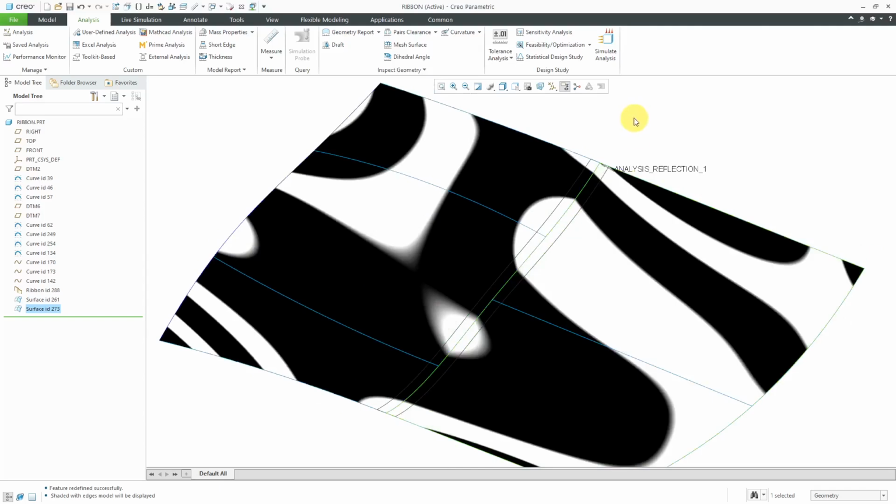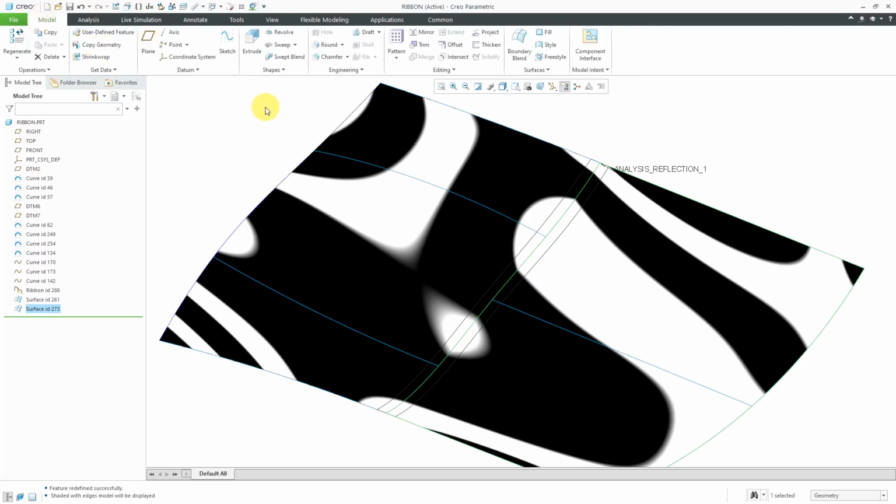intermediate surface. Now honestly, myself, a lot of times I do this manually when I'm doing surfacing. I will use the offset command to offset some edges and then create a boundary blend between them, but the ribbon surface pretty much does that as well, so maybe I will actually start using that more often.